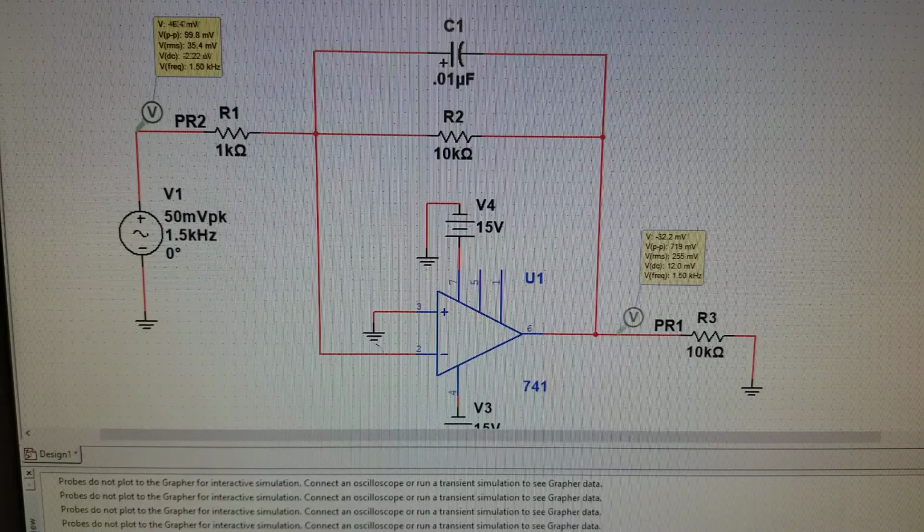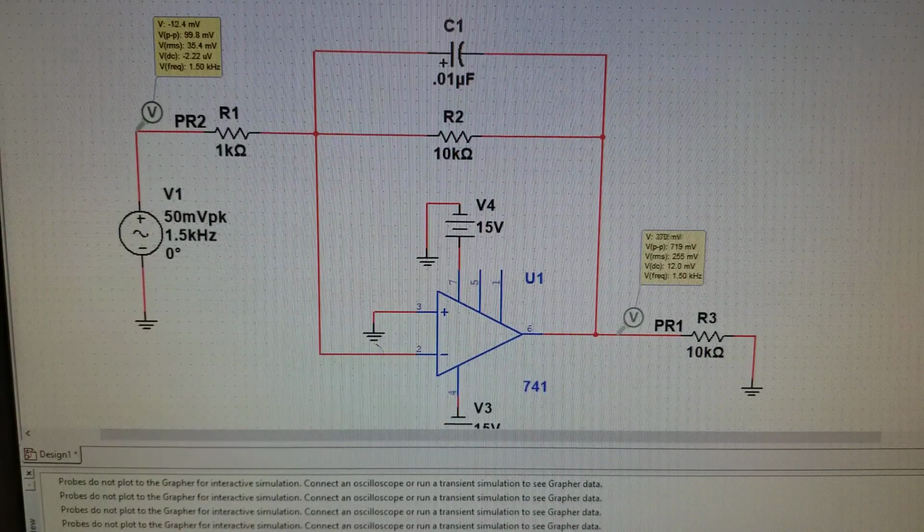So finally, step 6 tells us to measure and record the cutoff frequency. The cutoff frequency is when the output voltage is 0.707 of the input voltage. Whatever the frequency is, when you're at about 70% is considered the cutoff frequency. So with our 1 volt that we had at 100 hertz as our output voltage, we could calculate that our cutoff frequency would put us at 0.707 volts, or 707 millivolts.